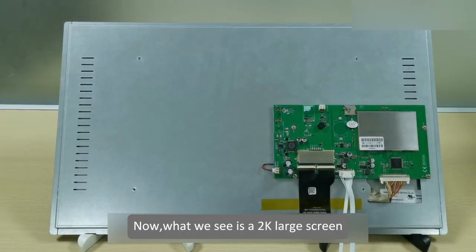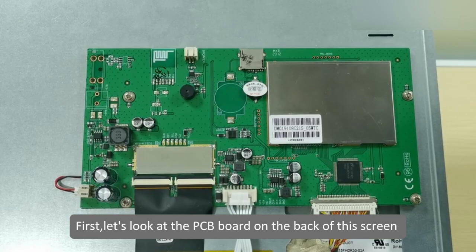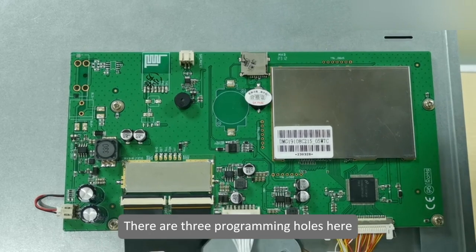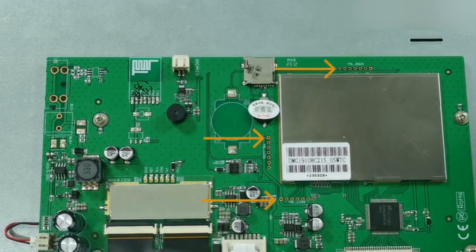Now, what we see is a 2K large screen. Next, let's take a look together at how to program the kernel through the PGT05. First, let's look at the PCB board on the back of this screen and see what the differences are between it and our common standard screen. There are three programming holes here, which are the programming hole for T5LD and the two programming holes for the coprocessors on the left side and at the bottom.